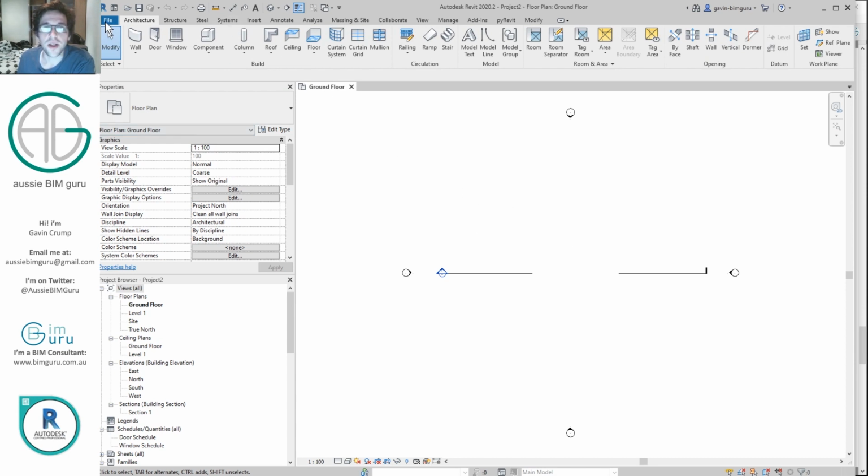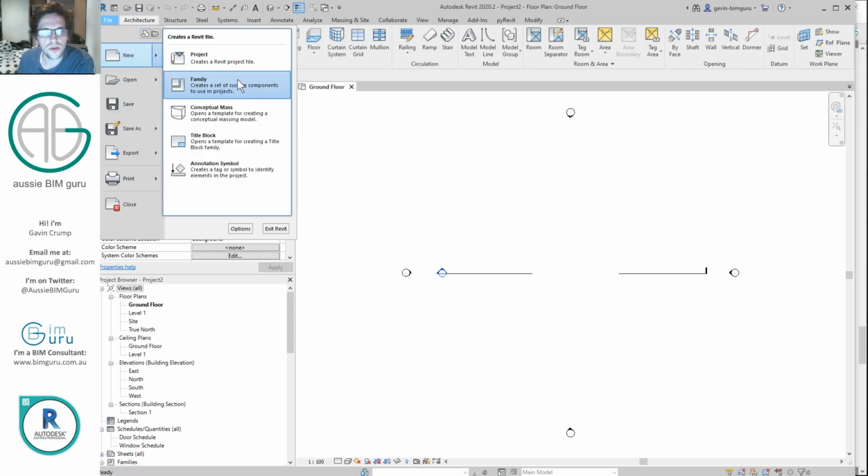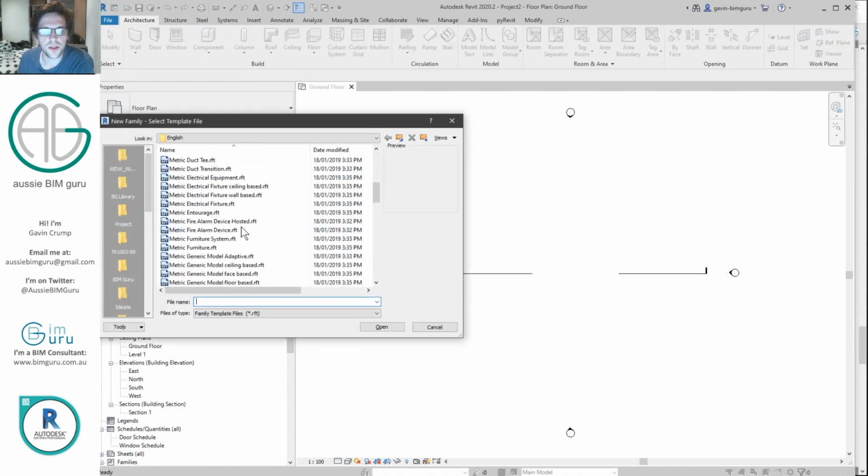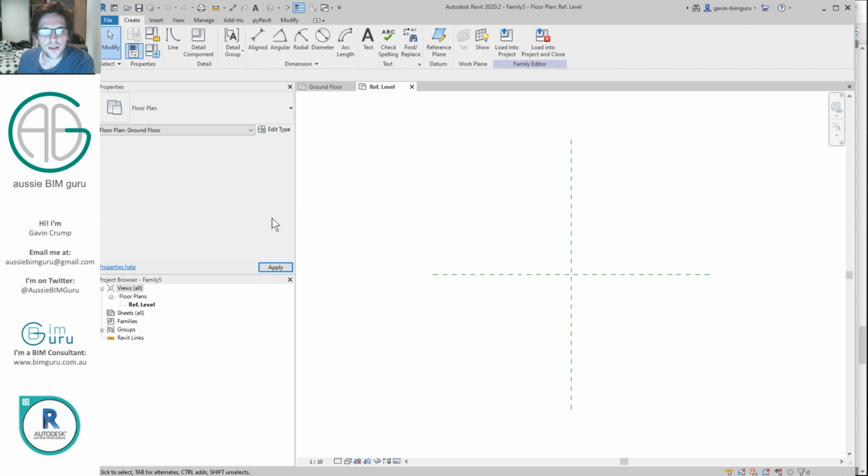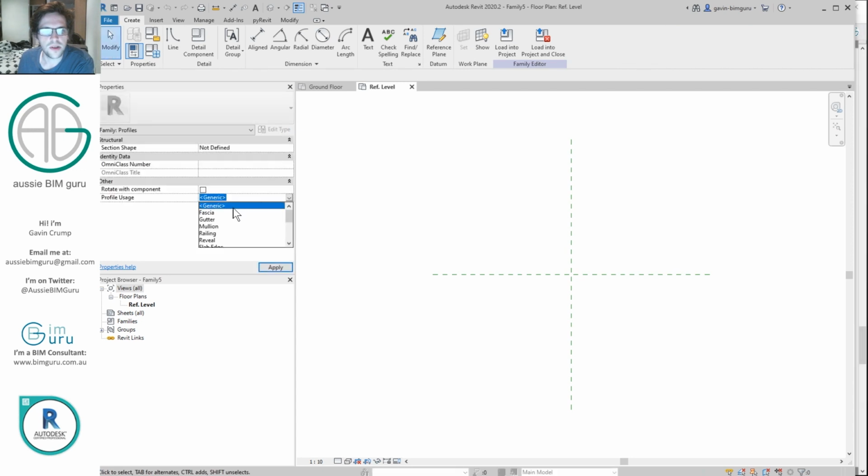I'm going to start by creating a profile family. So I'm just going to go new, and I'll hover over new family. And in this case, I'm just going to go down to profile. And in this case, it doesn't really matter what type of profile we're using. I'm just going to use generic in this case. And I'm going to start building my door frame.